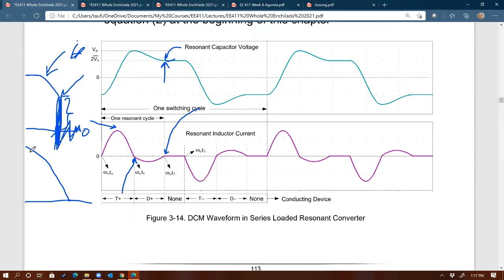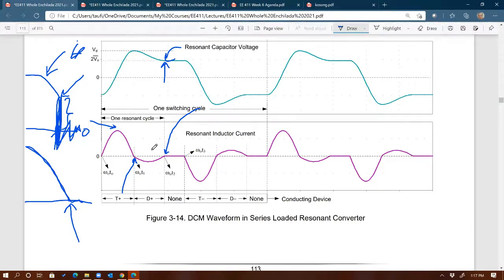But when the diode current goes to 0 naturally, and it turns off, and you don't want it to conduct anymore, then it will naturally go off. In this case, there is practically no reverse recovery energy because it's 0 amps. So for this mode, it is okay to use a PN junction diode, a slow diode, because the current naturally goes to 0 when we turn off the diode. Does that make sense?